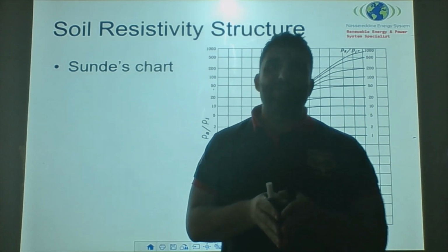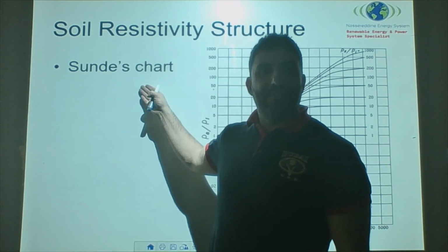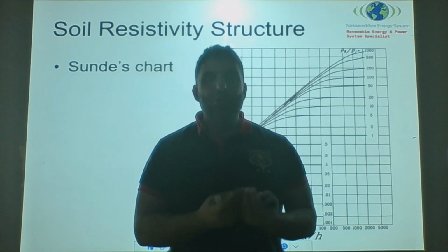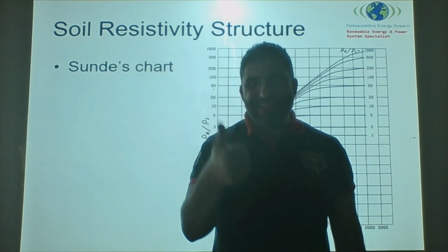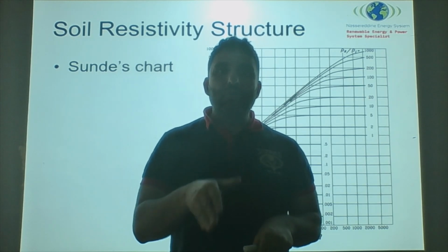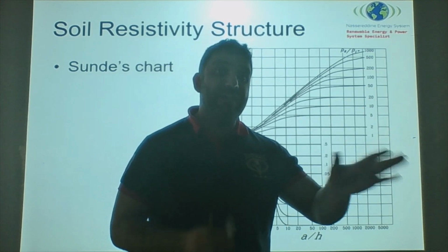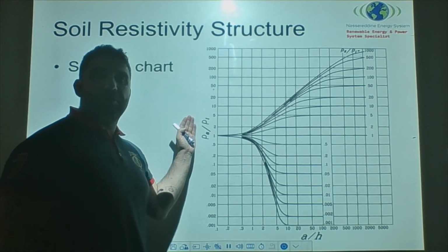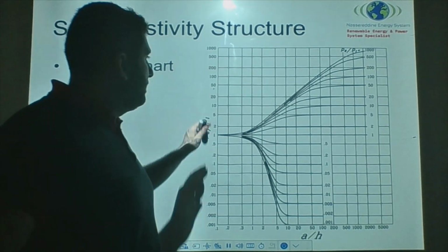During our next lecture, we are going to capture how to use this data, how to use the soil structure that we obtained to compute the actual resistance of the earth grid embedded into our soil, and how to calculate the actual step and actual touch voltages, not the allowable limit, the actual one, which is heavily impacted by our calculation of the soil structure.